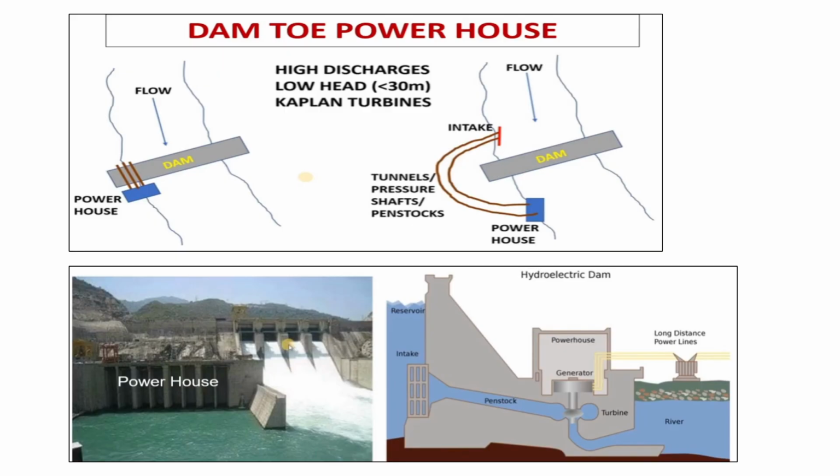One is directly having the powerhouse at the downstream of the dam blocks, that is, water intakes going through the dam body as shown in the bottom image. The other layout is using tunnels. These tunnels are taken around the dam body through the abutment, with the powerhouse at the dam toe. So careful consideration is to be given to the selection of the dam axis.